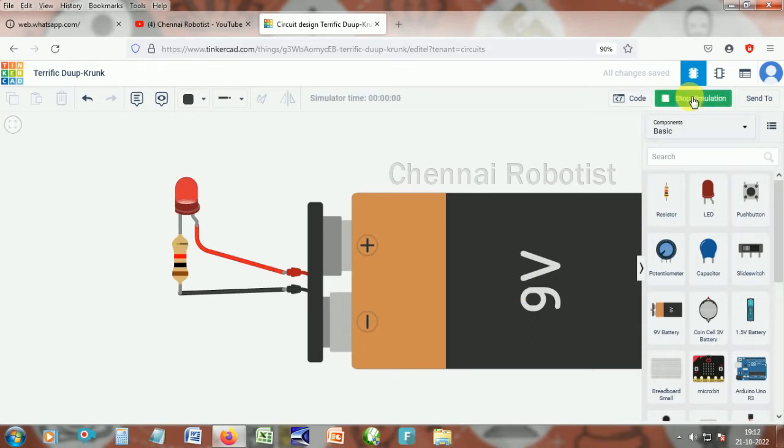Oh, now our LED is glowing. So now you know what the work of a resistor is. A resistor is basically a resistance to current. So out of 9 volts, the resistance drops 6 volts and gives only 3 volts to the LED. It's not exactly 3. It's about the current that's pulled through this resistor. So the resistor here is a subtraction. Let's learn that now.